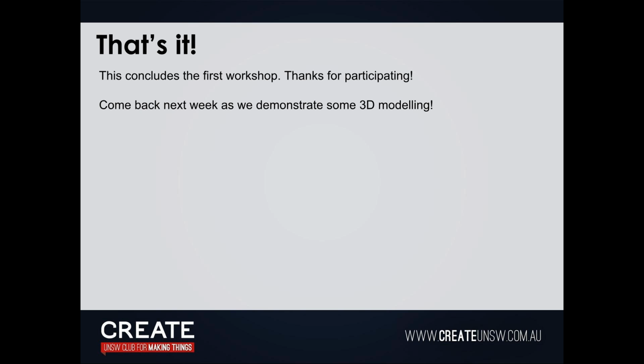Let's just start with a simple circle. Human fingers are about 15 millimeters thick, right? So there's your base profile. Now I'll rotate it this way so you can see. Next you hit E and extrude that up.